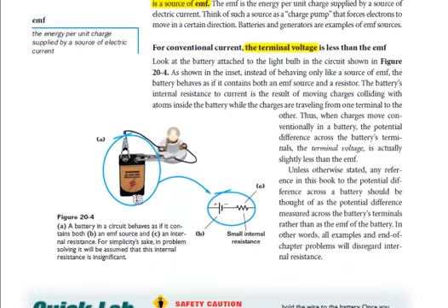So if this battery is rated for 1.5 volts, actually this is a 9-volt battery, so we'll say 9 volts. The charge leaving one terminal will have 9 joules per coulomb, returning back to the other, they have 0. My battery would have to fill them back up to 9 volts. But the battery itself has internal resistance.